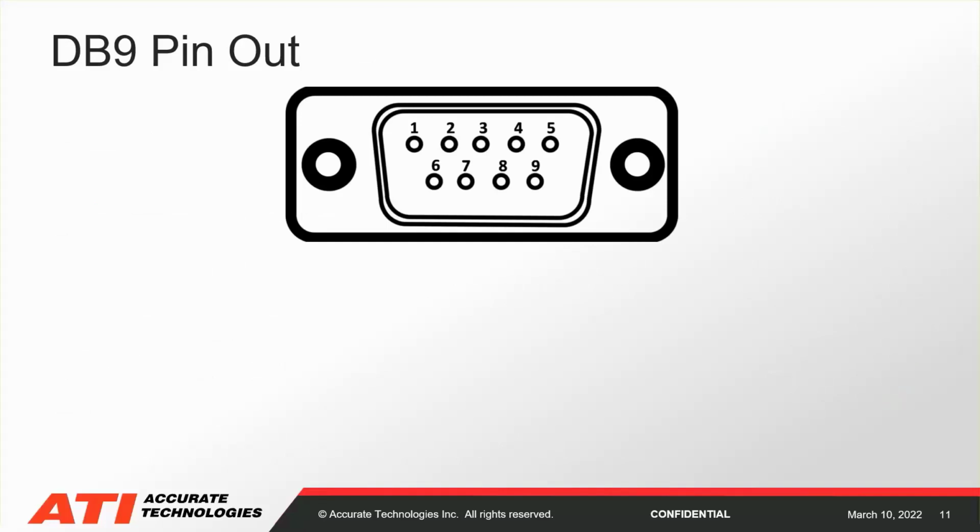Now, one of the first differences between CAN and LIN is the pinout for the hardware interface. So here you see a typical DB9, which is used on all of the Kvaser and ATI CAN interfaces. And here we see your typical CAN pinout, where 2 is CAN low, 7 is CAN high, 3 is ground, and 5 is shield.